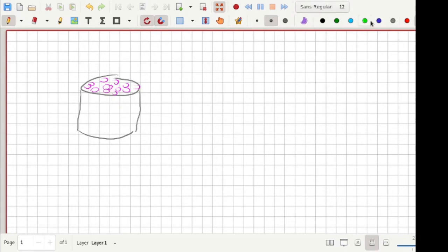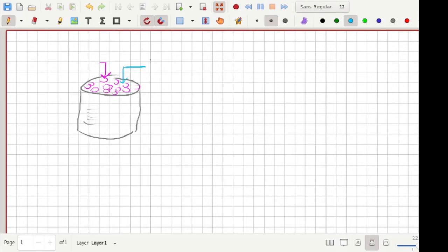So we say that this is an undisturbed sample because to some degree it preserves the internal structure of the material. And the other thing about bulk density is that inside the core, inside this whole volume of the core here, you're going to have your solid particles, which I'm indicating by these pink spheres here, and you're going to have pore space, which is empty space.